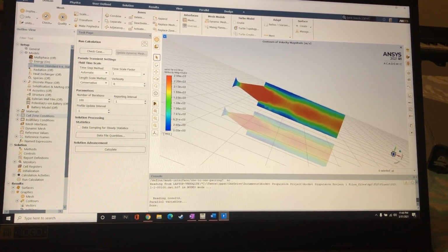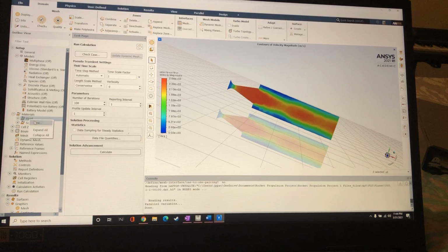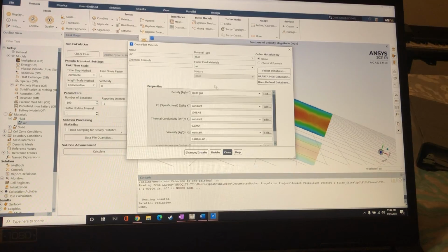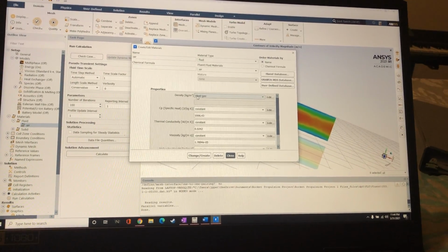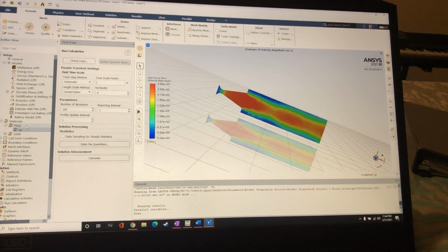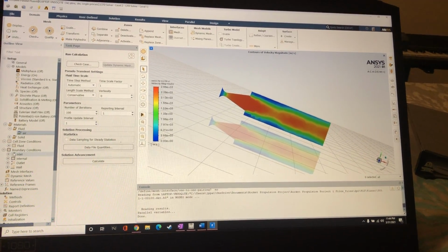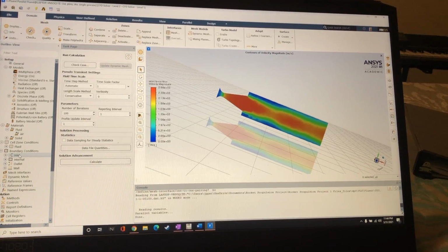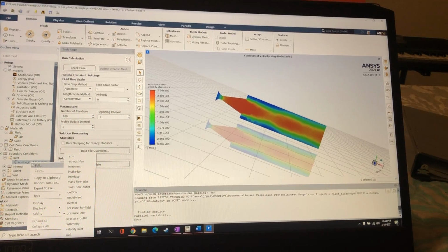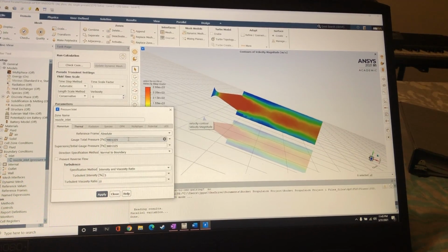Oh, I changed it to ideal gas behavior. If we go into here, I can show you that. I had to set the behavior of the gas to ideal, and I had to set the molecular weight to 20, as was stated in the problem. I had to change the parameters. I had to change the inlet to a pressure inlet and apply the given pressure that was stated in the problem statement, 9.7e6, I believe.